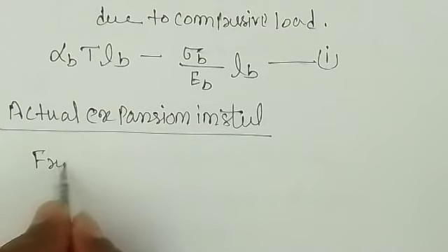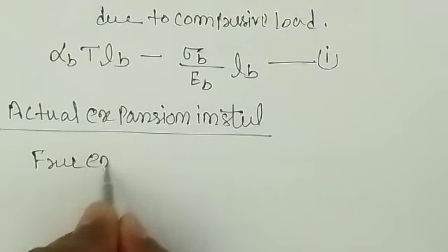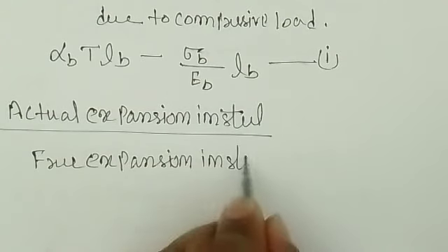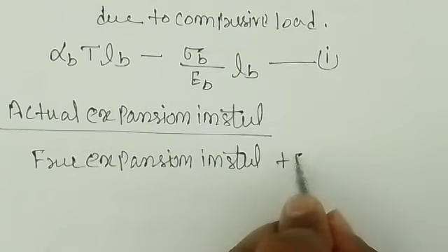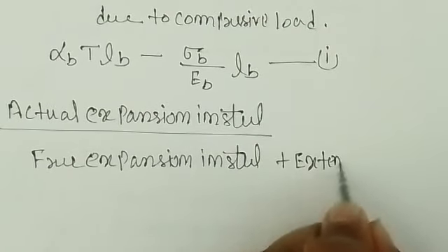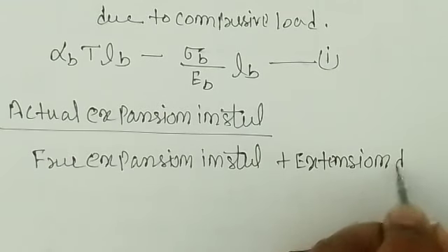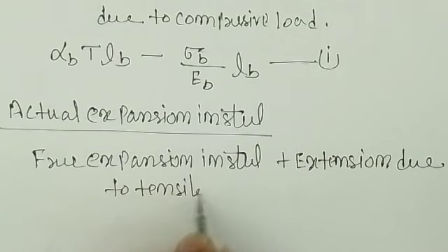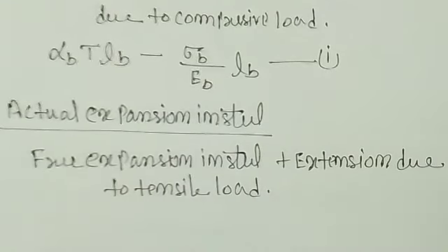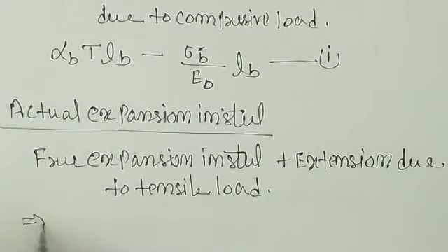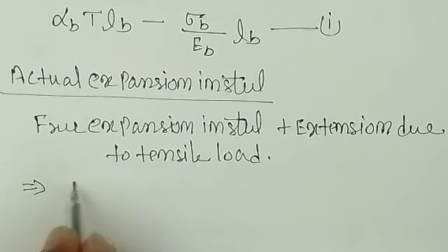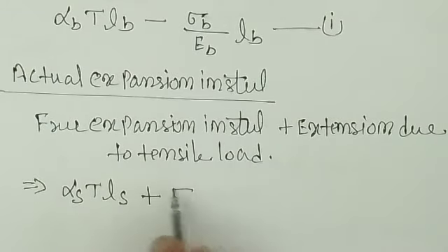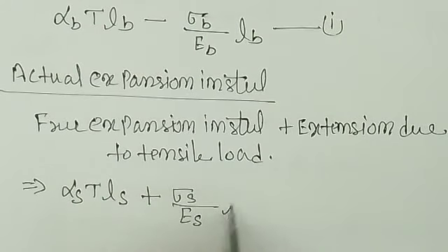You can say free expansion in steel plus expansion, that is extension due to tensile load, right? Due to tensile load. So free expansion in steel is what? That you can say alpha S T into LS plus sigma S by ES into LS.